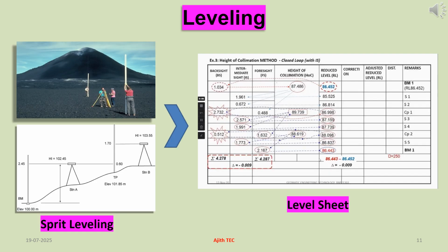This slide shows how to perform spirit leveling and data collection with the help of spirit level and leveling staff. Then required calculation and adjustment are performed on collected data and tabulated. Finally, prepare level sheet indicating required places' height with reference to Earth's surface.